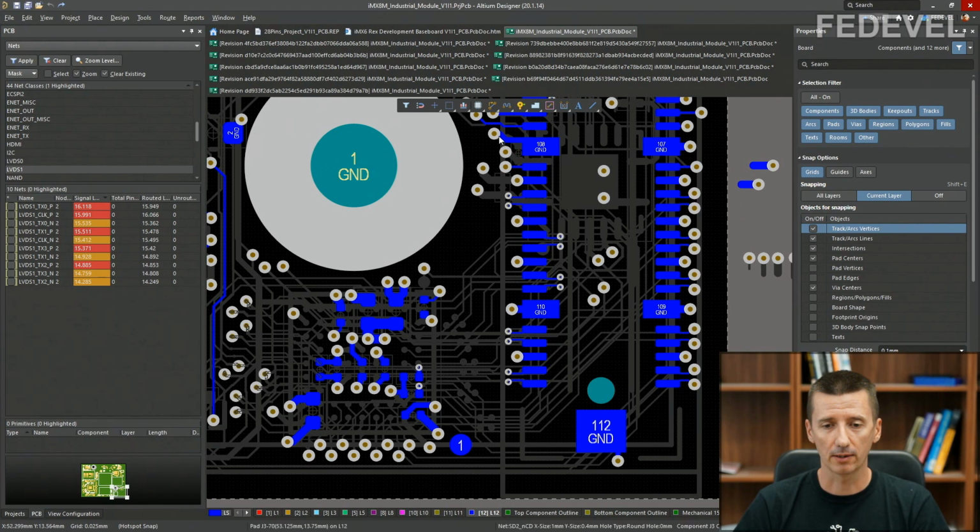Because this is a completely new design, there is nothing about compatibility with previous revisions or boards, we could play with the pinout of this board-to-board connector, and this improved this LVDS layout a lot.